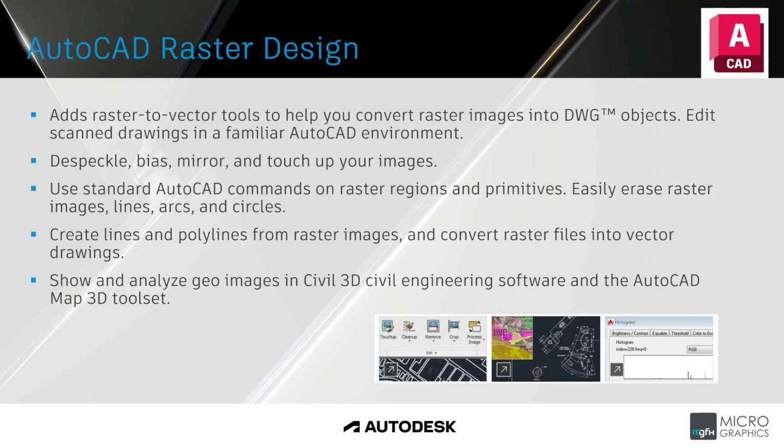So you scan the drawing in, and you're going to get a whole lot of dust marks in it. That's just fact. It's going to happen. You can't get away from it. So they've got this awesome thing called despeckle. It takes a look at all the little dust parts, which come out as little pixels. You say anything smaller than 5 pixels, delete, boom, done. Despeckle the whole thing, so now you've just got your lines.